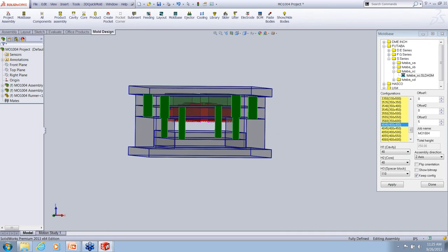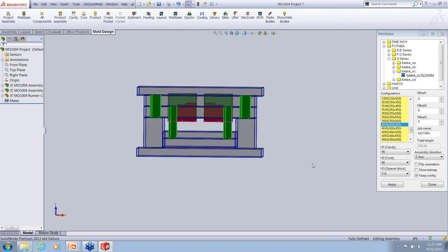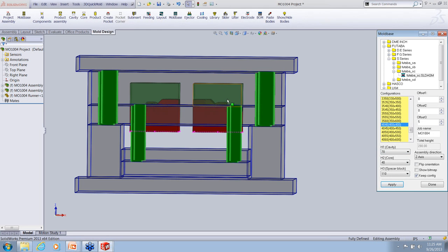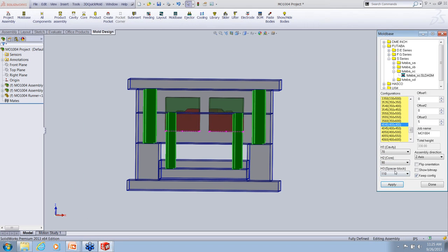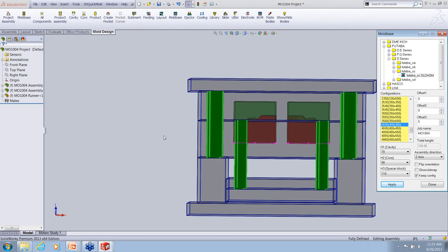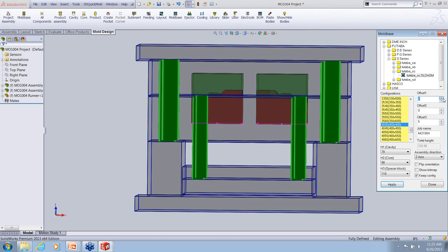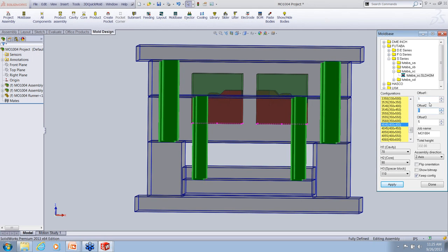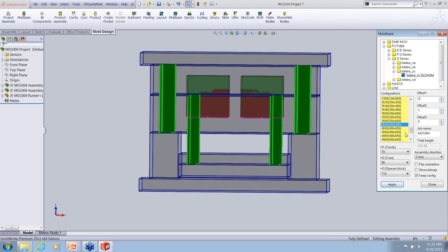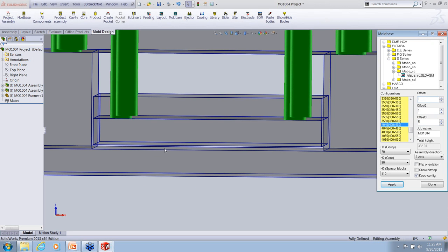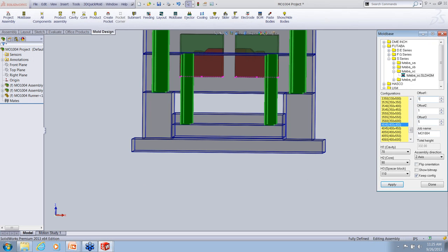By seeing the preview, let's define the sizes, since the core and cavity size will vary every time. So here itself we can define the plate thickness. Let's have a look here. This is going to change immediately. So I'm going to change the core dimension here, and then immediately you can also change the spacer block heights. If required, you can control the gap between moving half and fixed half using these options. Maybe just a 0.5 gap on both sides, and you can also control the offset between the ejector assembly and bottom plate by providing rest buttons. This gap you can control here.